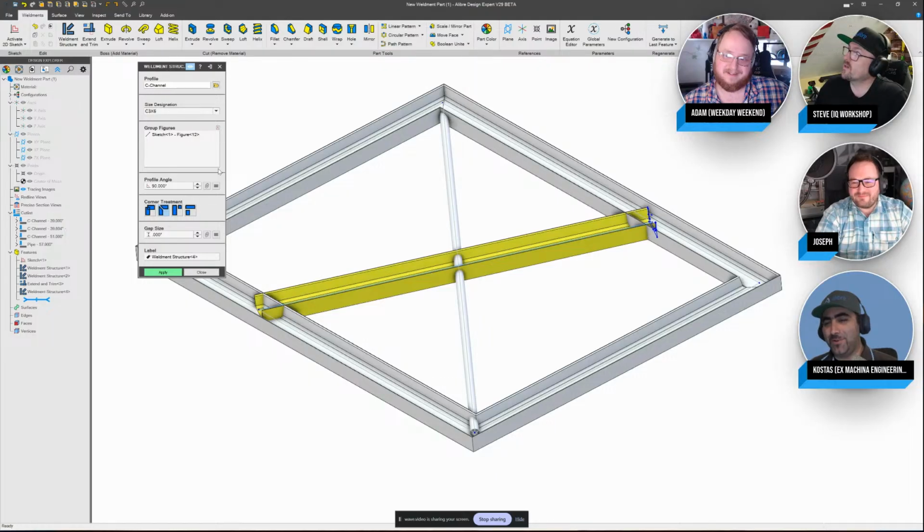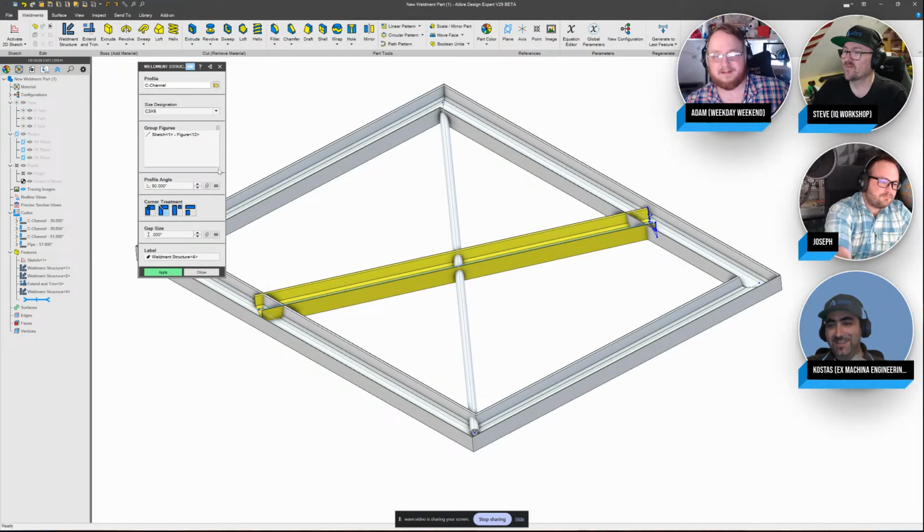Now, and I'll tell you one more thing. I used SolidWorks weldments for a client recently. You add the profile of an aluminum extrusion, 80-20 or whatever, right? And you could make it bolt together. Oh yeah. You could just lay out a frame for a whole 3D printer in like 10 clicks. In seconds. Yep. There you go. You got it. That's why I'm so excited about it.